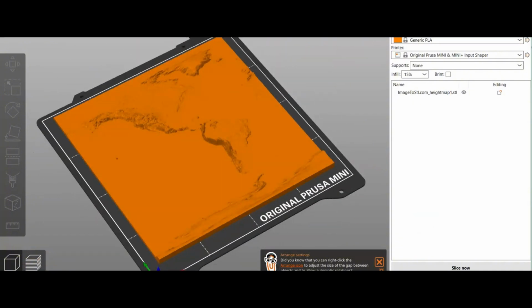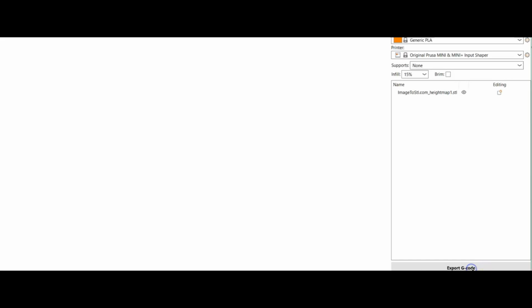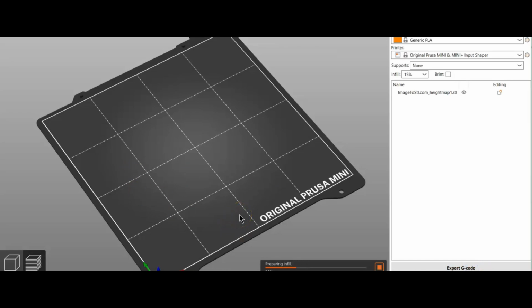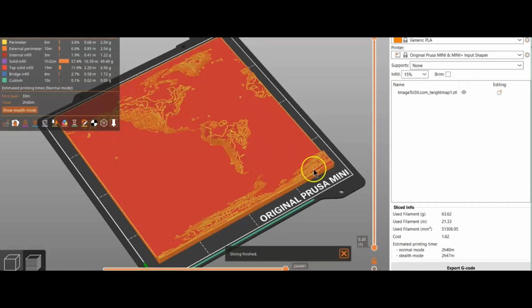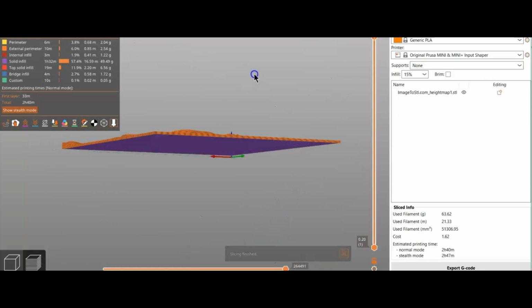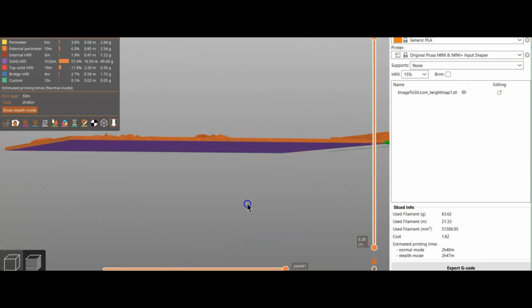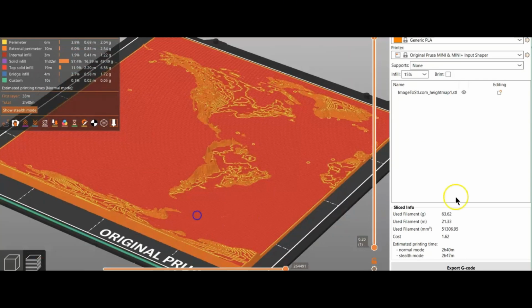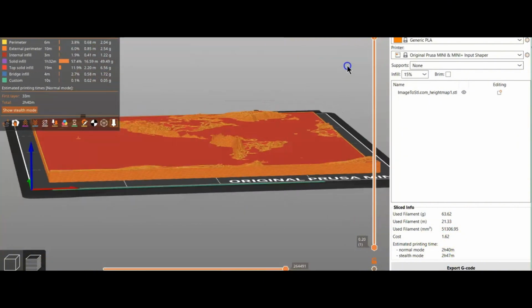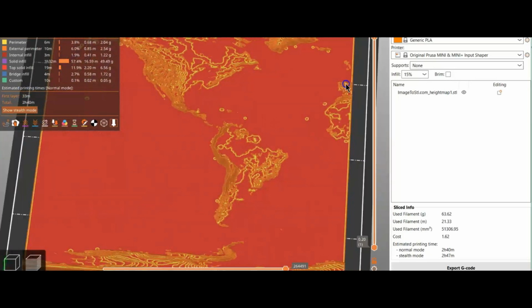So with this piece, now you can just print this. Let's see, you can go to slicing, wait for that to do the infill. Let's see how that looks. All right, here it is. This looks pretty good. You maybe want to reduce the infill because this will take a minute. It says it'll take about 2 hours. Looks pretty solid.